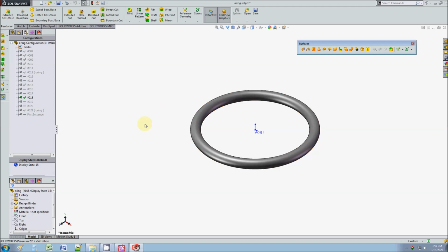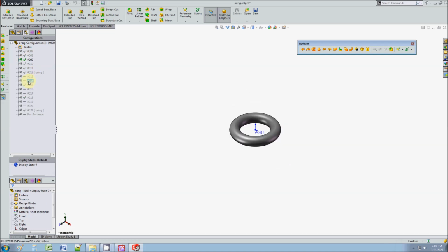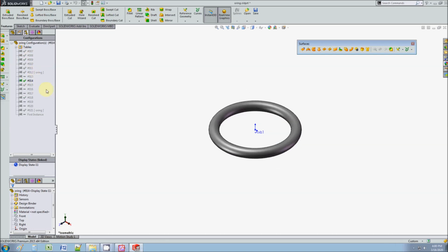So this is really good for optimizing. You can use configurations to not only build a universal O-ring, but also a universal bolt, a universal washer, and a universal nut. Okay, some of that common hardware you use all the time in design. So when you design that universal model, you import it on your assembly and you just double click. You say, hey, I want a quarter 20 bolt. I want a quarter 28. Make it longer. And that can save you a lot of time because you don't have to import the model from scratch, remake it, delete it, re-import from the supplier.